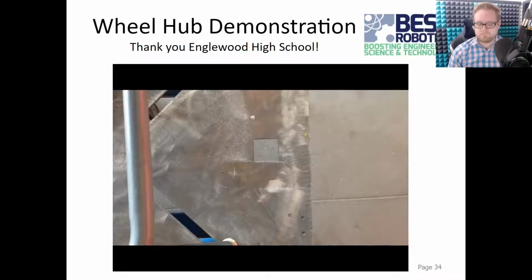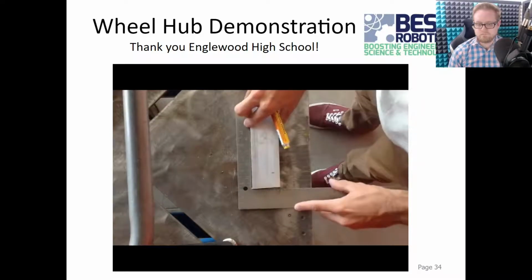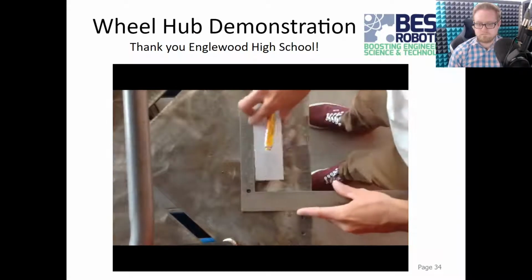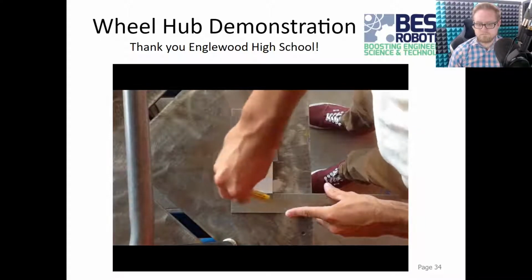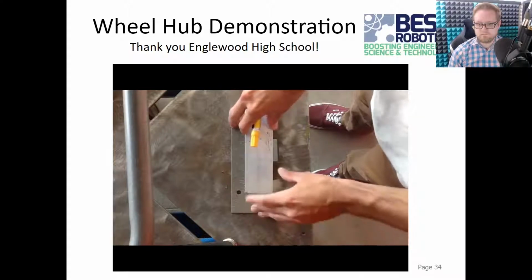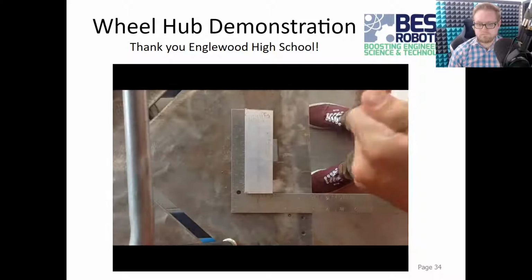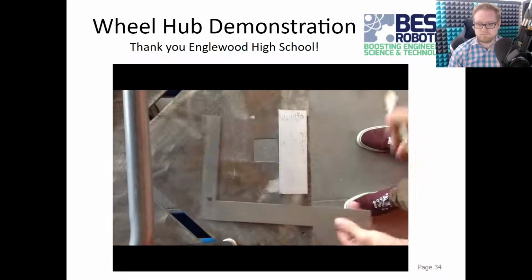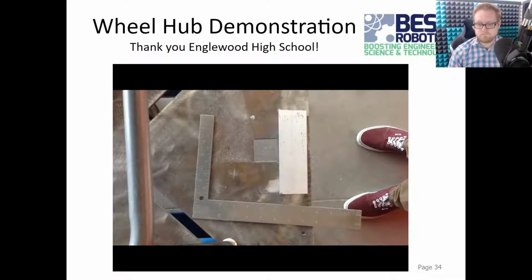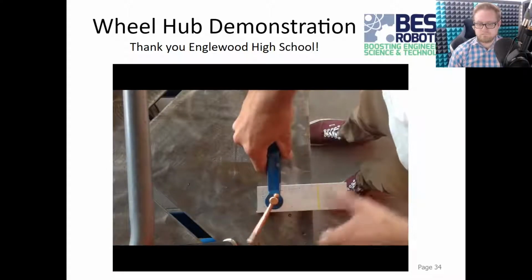The first thing you're going to need to grab is an aluminum brick. You're also going to need to grab a speed square and a marker. Line up the aluminum brick with the most flush side to the ruler. You want this to be 2 by 2, so we're going to cut 2 inches. So this is where I'm going to mark it. As you can see here, I have it marked at the 2-inch mark, which is going to give us a 2-inch square. Clamp the brick to the edge of a table.